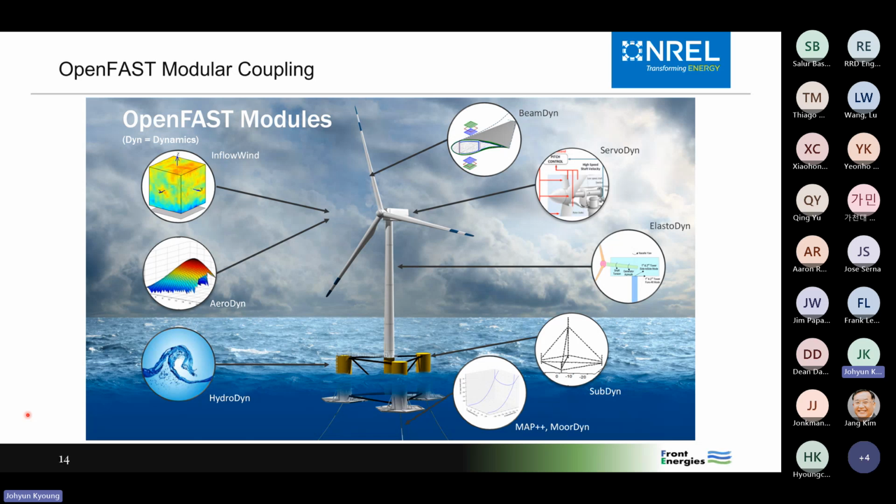Yeah. So basically, the bottom of ElastoDyn is a 6-DOF rigid body. And then we have a tower, and right now the tower in ElastoDyn is just 2 bending modes, 2 fore-aft, 2 side to side. There's another development coming. It's not started yet, which is why it's not on the list. But we are adding tower torsion here soon. But that's in ElastoDyn. So if you just want a simple, mono tower with bending and torsion, that's ElastoDyn.